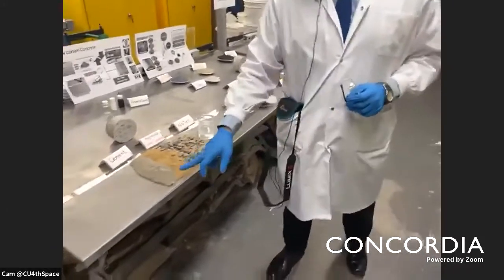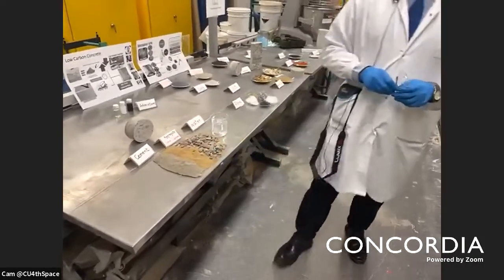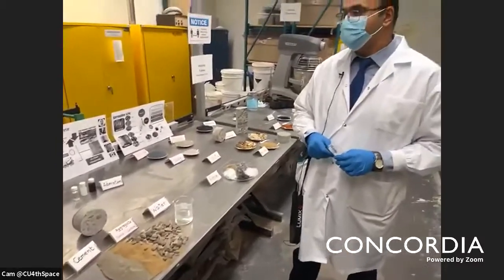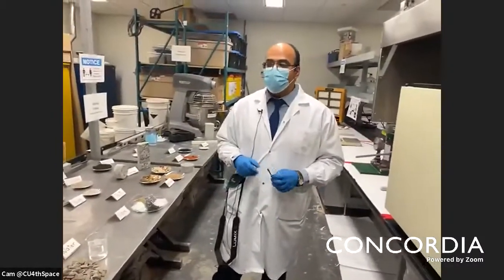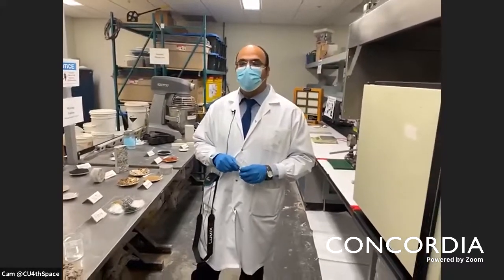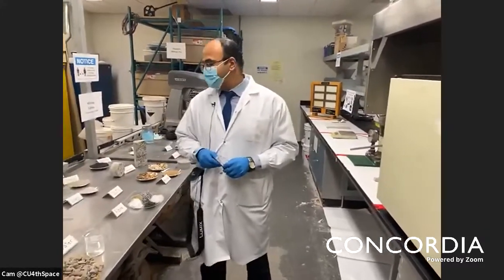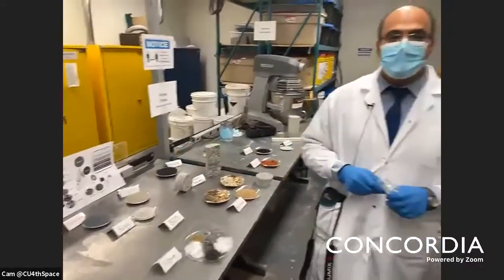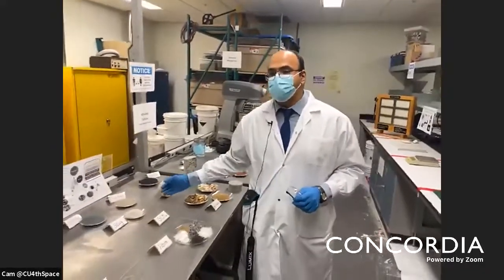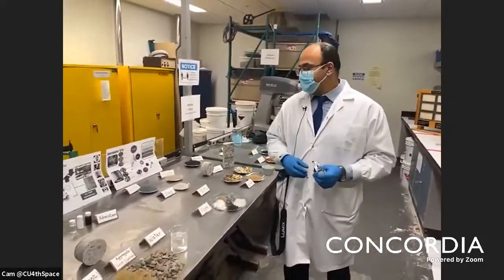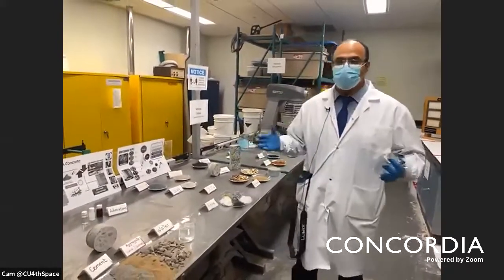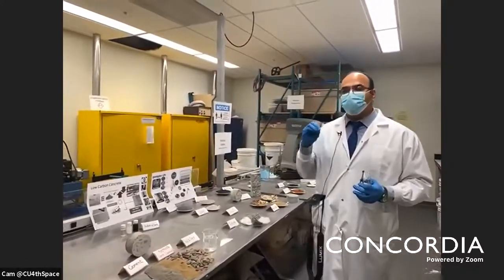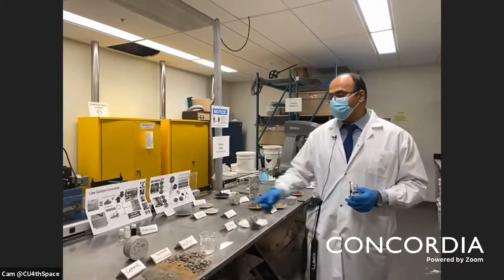Therefore, we would like to reduce the amount of cement. How can we do that? Simply, we can start replacing a high portion of the cement by supplementary cementitious material. Nowadays, we are working in our lab on what we call alternative binding material, like alkali activated material. Here we try to activate such supplementary cementitious material, or in a more precise way, alumina silicate material, with activators, and therefore we can produce zero cement concrete, concrete without cement, okay? Because once we activate this, we will have a material that's going to perform the same way as cement when we mix it with water.